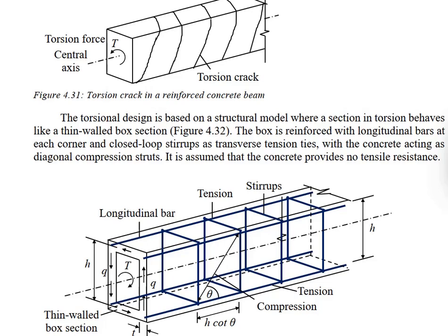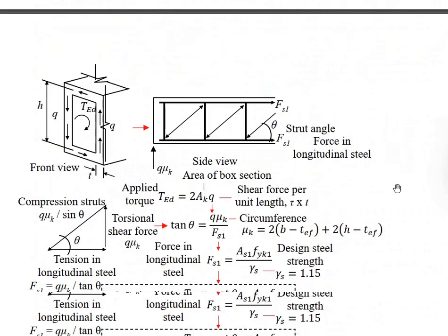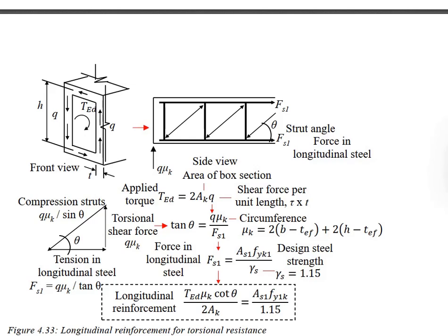An imaginary truss model is assumed, and then based on the torsional load applied onto the member, there will be shear flow. This shear flow is considered as the external load acting in the middle, through derivations of the trigonometry, as well as the fundamental principles for the derivations of the forces in reinforcement and concrete.